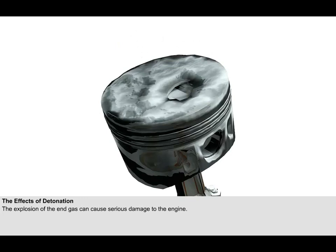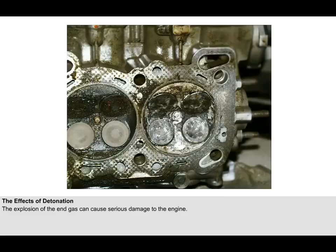The explosion of the end gas can cause the piston crown to burn and eventually to collapse. This picture shows a piston which has been severely damaged by detonation. The piston crown has been burnt and eventually it has disintegrated. Overheating of the combustion chamber can also occur. This may cause the valves to split and distort. It might also damage the spark plug electrodes. The damage shown here is consistent with being caused by detonation.